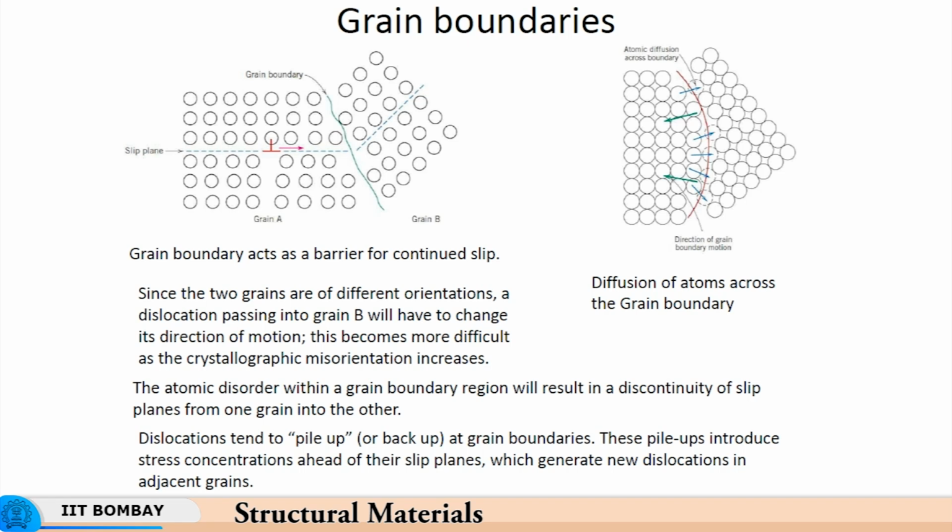For example, in case of iron, carbon atoms are added, and that makes it steel, and then the strength of the steel comes from these interstitial carbon atoms impeding the movement of dislocations. Now the resistance to deformation of the material increases as the impedance to dislocation movement increases.